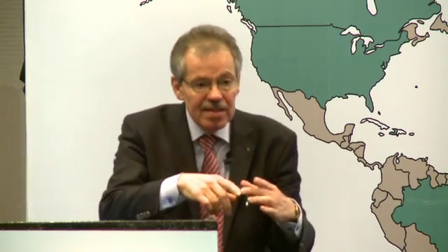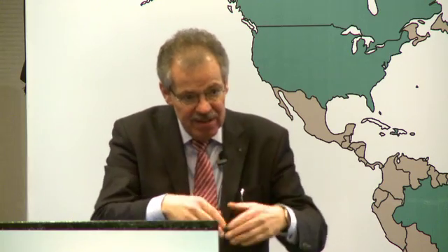But as it loses no water, we term this basic creep. If the same specimen, same concrete, same age at loading, is unsealed, water is given to the environment. You subtract the deformation part from drying shrinkage, but you find then an additional creep, much higher than the basic creep. And this creep we term drying creep.